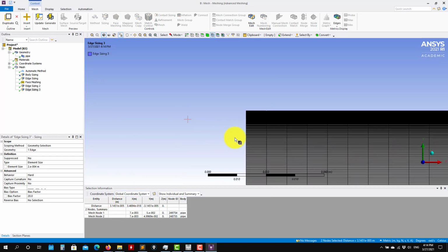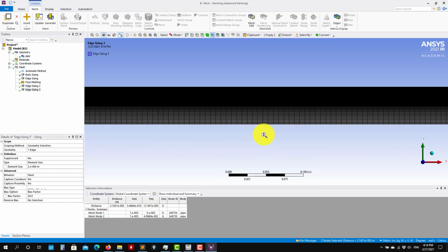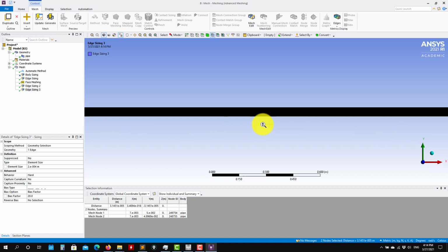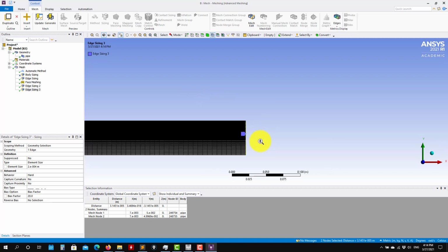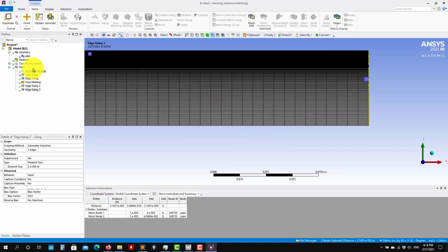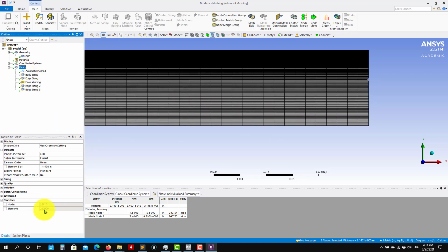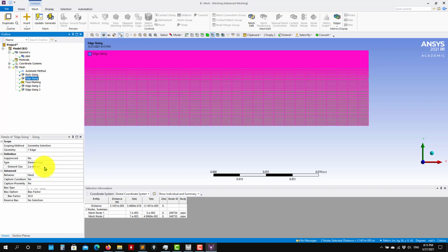So we're there. See, verify the mesh that we have, and also check the other extreme. So we have this mesh. Always control the number of cells. You have 250,000 cells. Probably I had it too much, but let's reduce. Instead of using 0.0, let's put 0.05. Okay, this is okay.